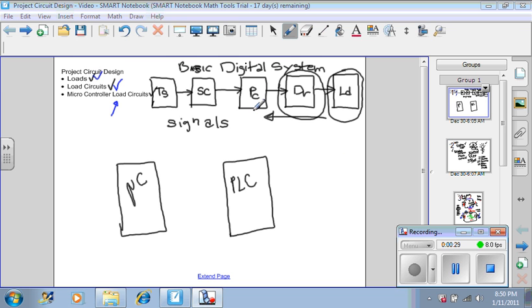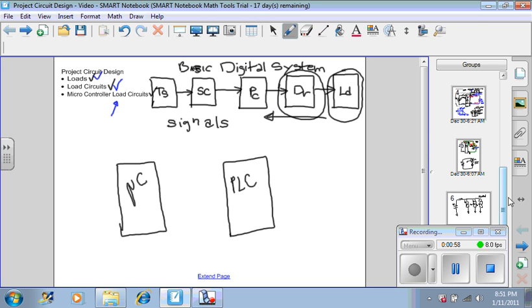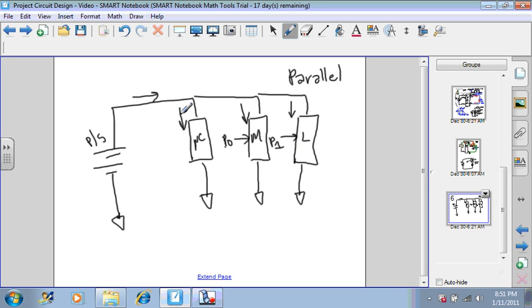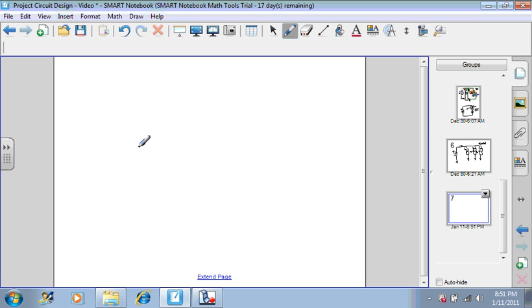The processor here is a digital machine. Therefore, it only has two states, on and off. And you have to read the data sheet in order to know what the typical on voltage is, what the typical off voltage is, and what kind of current it can provide. Also, you can read a data sheet to find out about how much current is needed to operate the transistor in the saturation region.